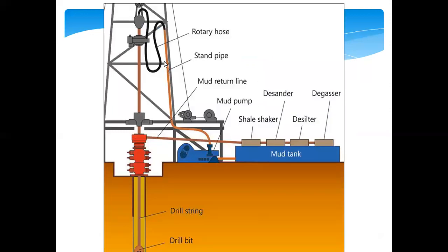The drilling fluid is pumped from this pump through the upright stand pipe and through a goose neck that is connected with a Kelly hose. This is the black Kelly hose, and the mud passes through this swivel and is forced down the Kelly pipe and goes to the drill string to get out of the nozzles of the bit and return back by way of the annulus to the flow line.